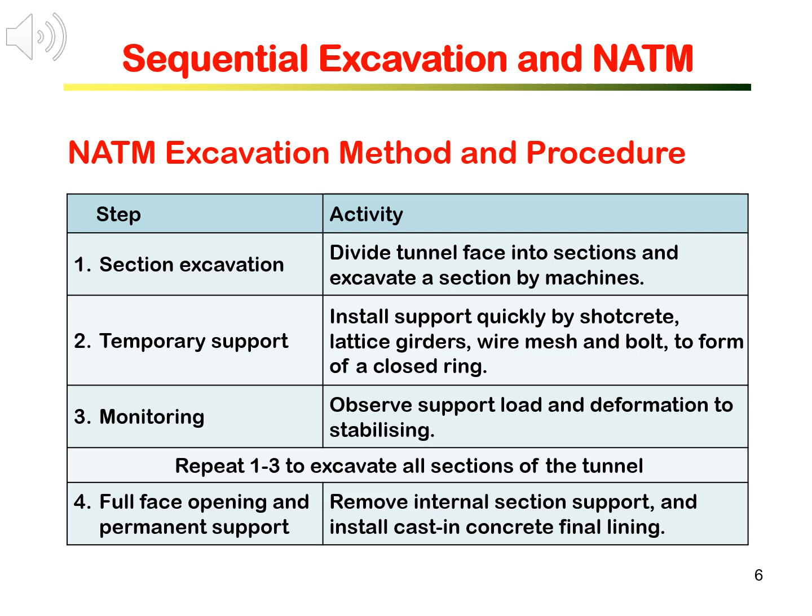Third, systematic instrumentation monitoring are conducted to observe support load and deformation to ensure the ground stabilizing. If ground is not stabilizing, additional support will be added. Systematic deformation monitoring is another highlighted feature in NATM.